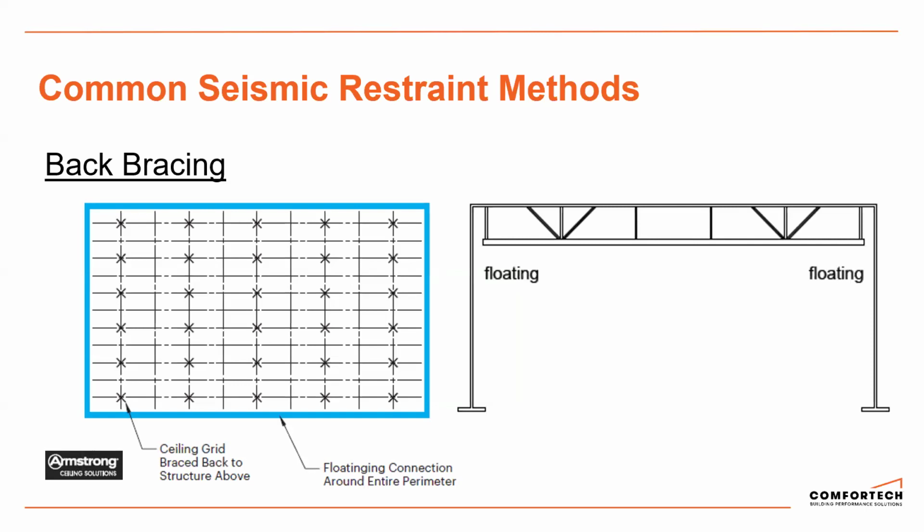So in areas of high seismic activity, Wellington, down on the South Island, up in Hawke's Bay, we often see back bracing required. And it does become a bit of a challenge when we're looking at clearances and plenum spaces. We've got back bracing we need to install. We obviously don't want that clashing with services.